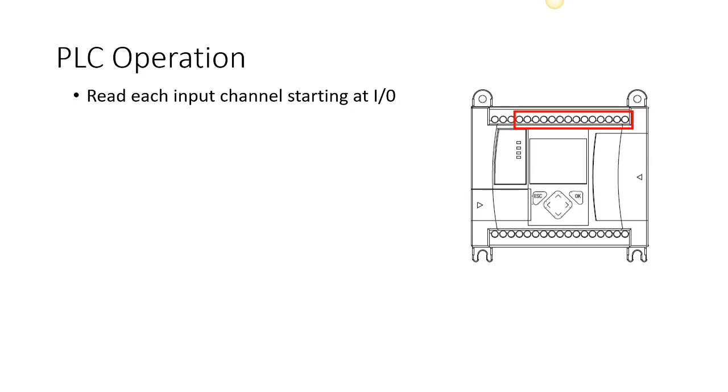As I earlier stated in the previous video, we have 10 inputs on this PLC. They're going to start at 0 and go through 9. That's something for a student to get used to. When we normally count in the world, we start counting 1, 2, 3, 4, 5. Well, we're actually going to be counting starting at 0, 1, 2, 3, 4. And that's going to make sense when we study binary number systems in a future lesson.